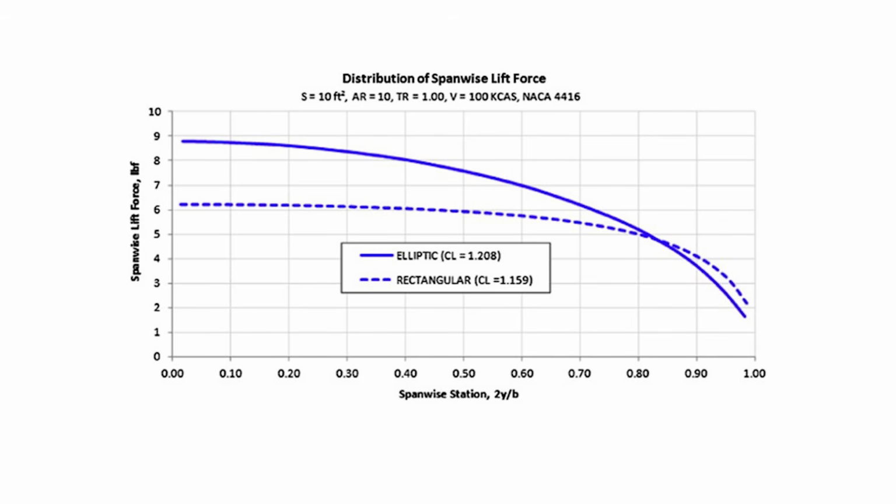Achieving an exact elliptical lift distribution in practice can be complex due to structural and manufacturing constraints, but understanding and approximating this distribution remains a fundamental aspect of aerodynamic wing design. Pivoting to a more structural approach, if you held the structural weight and root bending moment in the wing as constants, is there an alternate lift distribution that yields lower induced drag than the elliptical lift distribution does? It turns out that there is.